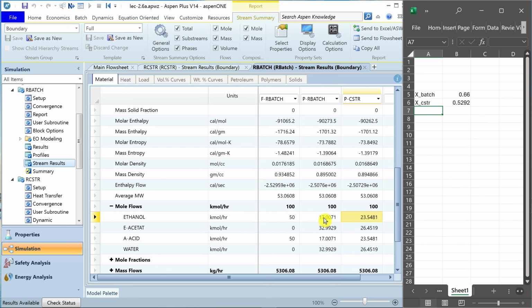I have already discussed how a batch reactor is simulated in a steady state simulator, but still these numbers for the batch reactor can be misleading, especially when calculating or comparing the fractional conversion with the CSTR. So the actual conversion of the batch reactor at any given case should depend on the actual number of moles or the composition present inside the reactor rather than the flow rates as displayed in the stream summary.